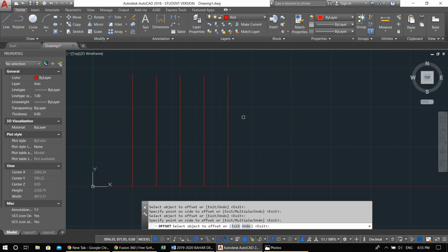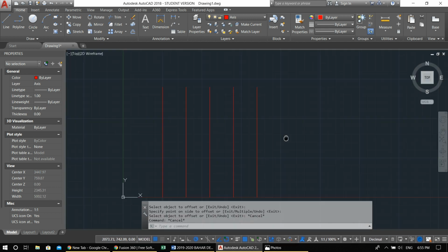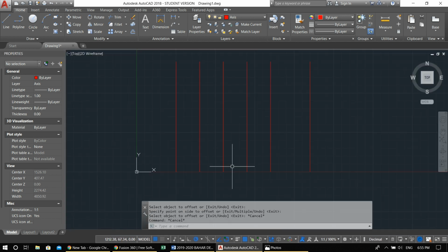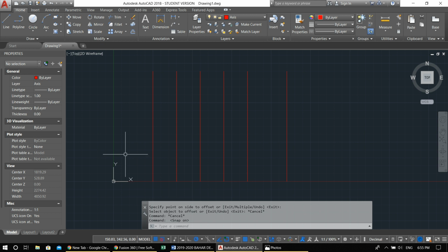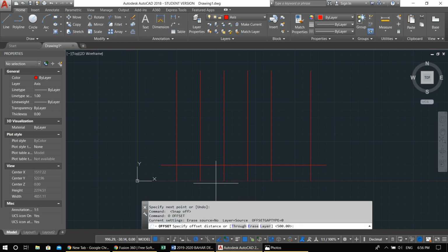Alright, so if you look at the drawing, we have our next axis, 500. So I press O, enter, 500. Here we go, next axis. So I want to turn my grid on again. I'm drawing now the horizontal ones. So I'm drawing this one. Let's have it as tidy as possible. F9. Press the grid off. Now I want to offset this. O, enter. First one is 300.